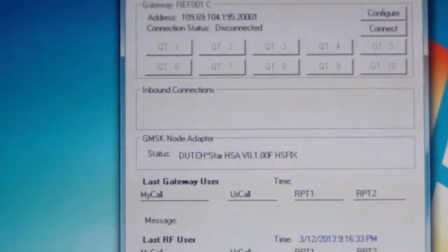Obviously that can cause an issue, because when I'm trying to control it remotely and it falls over, it may do what I've seen it do here at home, which is go into transmit mode. It hasn't done that remotely yet. That blocks off the frequency and will heat up the radio quick smart if left locked on, although I've got the timeout set fairly low at this point, about 3 and 5 minutes. Those should come into play if the software plays up. But you don't want that happening when you're away from home, you want nice stable software running.